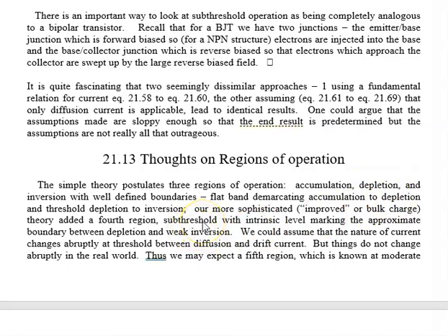That assumes that we go from basically no current whatsoever, current as in IDS, we get absolutely no drain current in depletion, and all of a sudden we get into strong inversion and we have a square law. Well, that is not terribly realistic, because things don't change quite that dramatically.